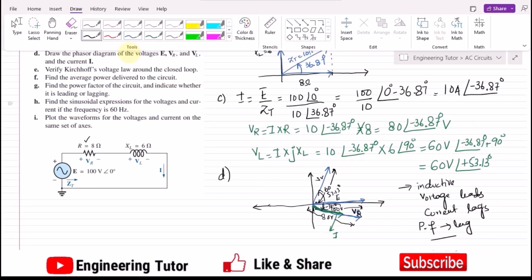Now moving forward, in part E of our question, we have to verify Kirchhoff's voltage law across the closed loop. According to Kirchhoff's law, E is equal to V R plus V L. What is the value of V R? It is already known, and that is 80 at minus 36.87 degrees. And the value of V L is 60, and the angle it has is 53.13 degrees.